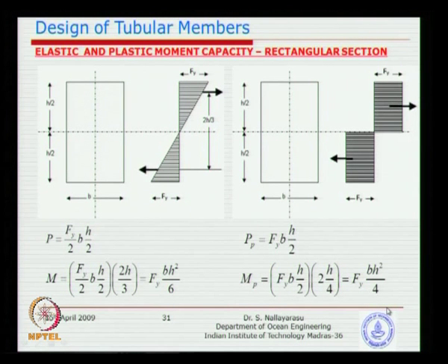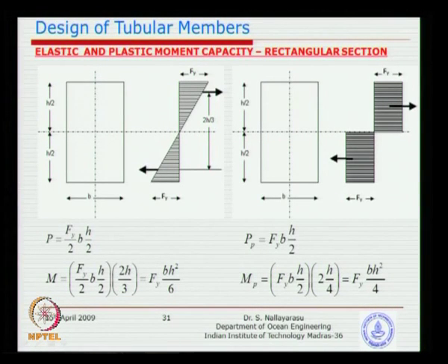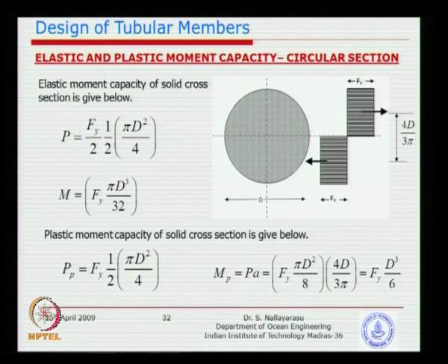The section modulus at the time of collapse, basically the section is fully yielded, whereas this section is partly yielded, only two locations at the top and bottom have yielded, elsewhere you see the stresses are far below the yield point. All of you understand this. The ratio is called the shape factor. Basically, because of this particular shape, the ratio of plastic capacity to elastic capacity is 1.5. So, plastic capacity is 50% higher. So, I am happy.